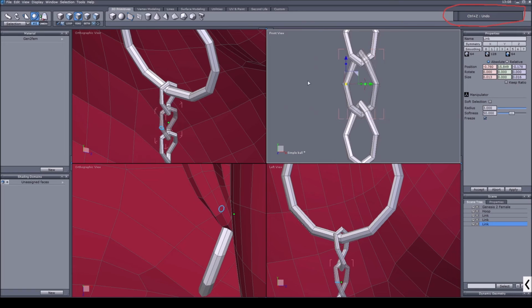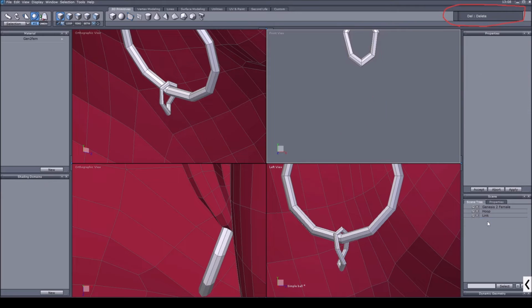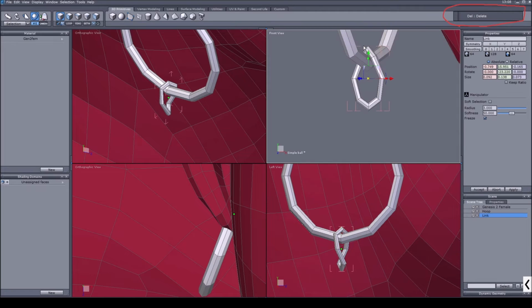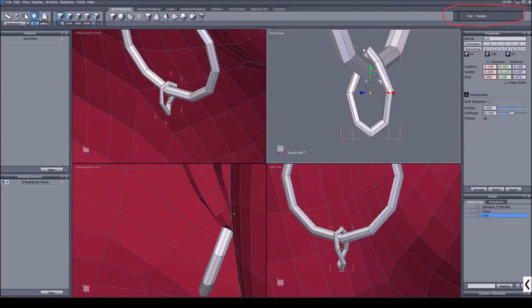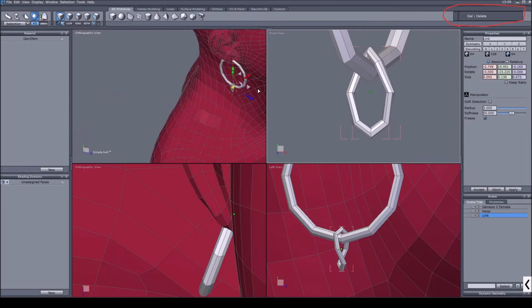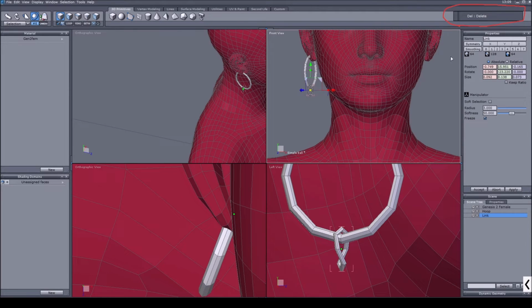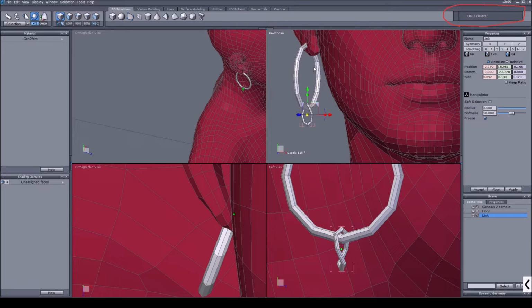So if you want to manipulate all of them, you can use Ctrl D, the clone function. Otherwise you can Ctrl V if you want to manipulate just one of the objects. For example, if you build something and you copy it to the other side of the head, then you want to do Ctrl V, Ctrl D, or at least unclone this first by pressing Z.